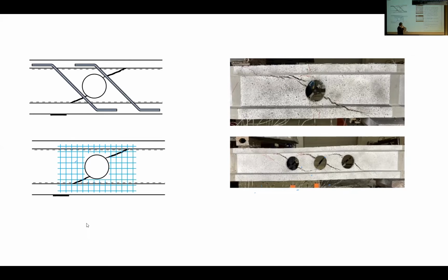The next question is, how do you find working with UHPC with white cement in terms of its technical performance? I think it's about the advantage of white cement. White cement is more reactive, based on our research result. Also, if you need colorful UHPC, you must use the white cement. Otherwise, the color shows a different color than we expected. It's not an absolute option, but it gives more freedom to generate the color as a base. A white base is more useful in our research result.